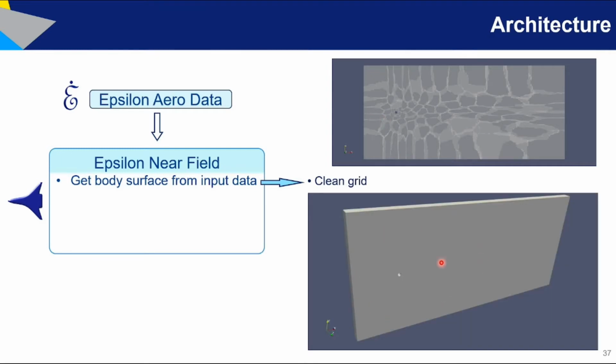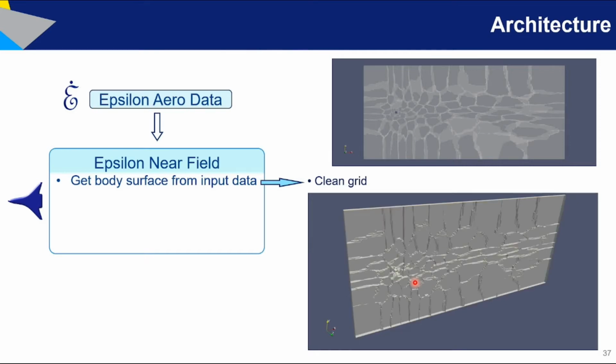So let's start with this example. This is a 3D case, the LES case that I showed you for the flow past a cylinder. If you extract surface, you will get rid of the internal volumetric cells, and you will theoretically retain just the external shell that contains the domain. But unfortunately, if you do just that, you will find out that there are internal surfaces.